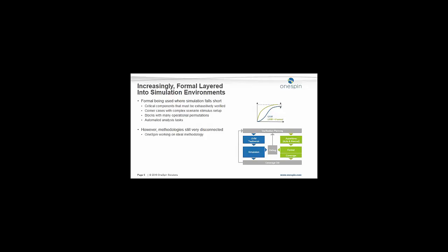Ideally, you want to use both together, because there are some types of corner case bugs that simulation would have no hope of finding. The previous speaker from Gila Logic was talking about some of the bugs that he found in the second examples. You've got something that only happens if you overflow some FIFO and some counter wraps around at the same time, while the design is in a certain mode, and then something bad happens.